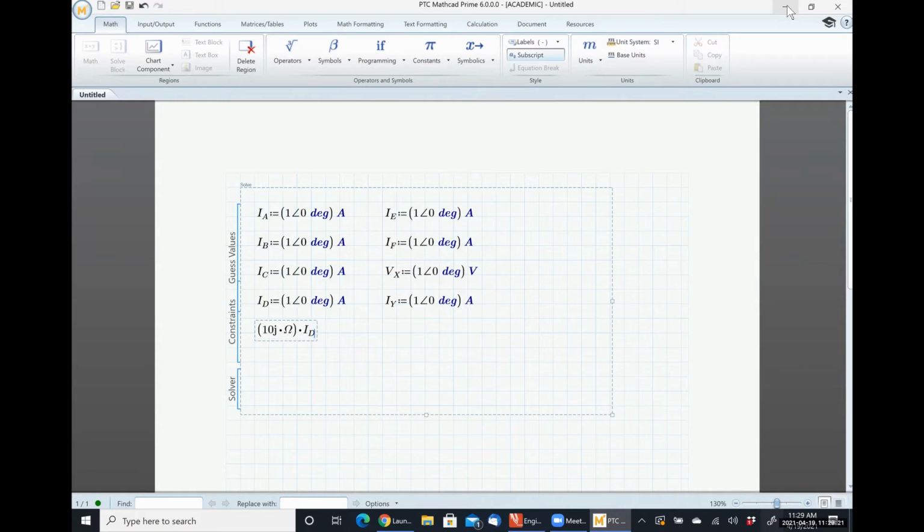The reason I'm choosing to implicitly multiply instead of letting MathCAD do it for me is that when you put things in parentheses, sometimes MathCAD takes that to mean that whatever you're typing is a function of something else, which is exactly not what we want. By explicitly multiplying over and over, it makes sure that everything is treated as a multiplication and gives us the answer we're looking for.